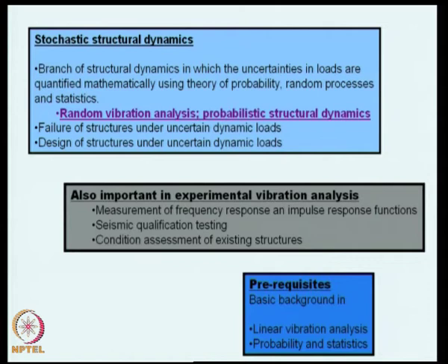The subject of stochastic structural dynamics also forms an important ingredient in experimental vibration analysis. For example, if you are interested in measuring frequency response or impulse response functions of linear systems, the measurement techniques are founded on principles of random vibration analysis.